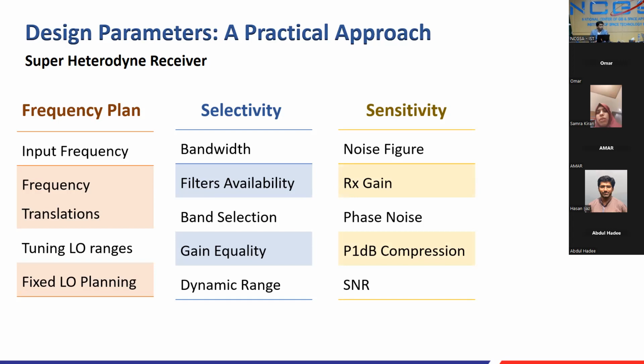Then the other thing is the receiver gain. Receiver gain is, for example, if you are receiving a signal at minus 70 dBm, then how much gain in the first step you need, for example, 48 dB gain to get the ADC sample. Usually the ADCs have a noise floor, for good to best ADCs, you will see they will have a noise floor of around minus 60 to 65 dBm. I am quoting 65 as upper margin, but usually minus 60, they cannot go beyond minus 60 dBm. And the noise floor of a receiver is around minus 80 dB. So there's a gap of 30 dB between them. So you need to have at least minimum 30 or 35 dB gain to bring that signal up, so it can be sampled in the digital domain to be displayed or the information to be extracted. So receiver gain, you have to plan that accordingly.